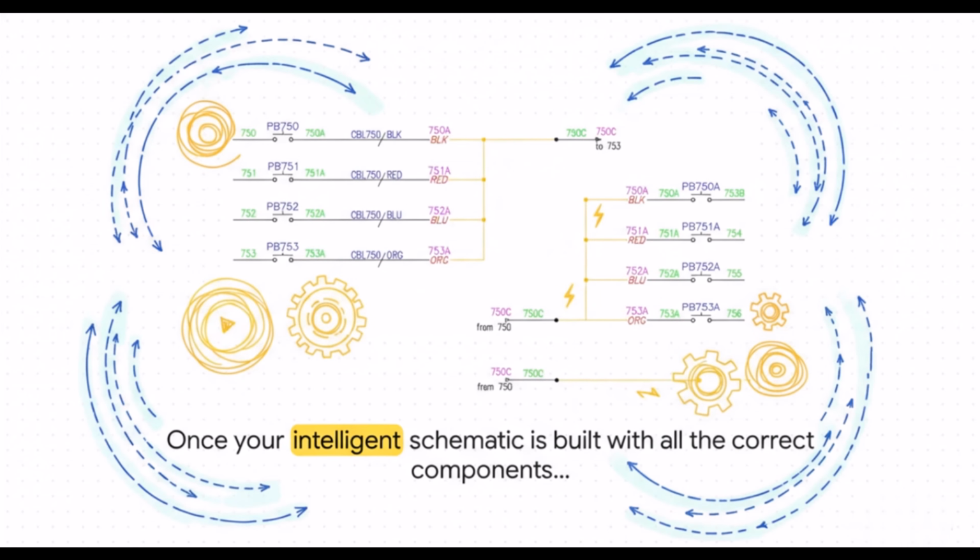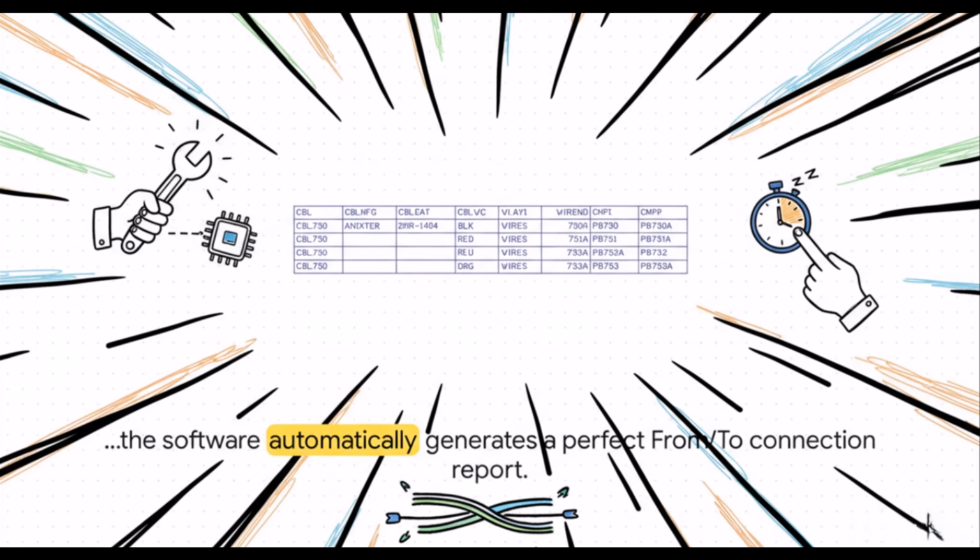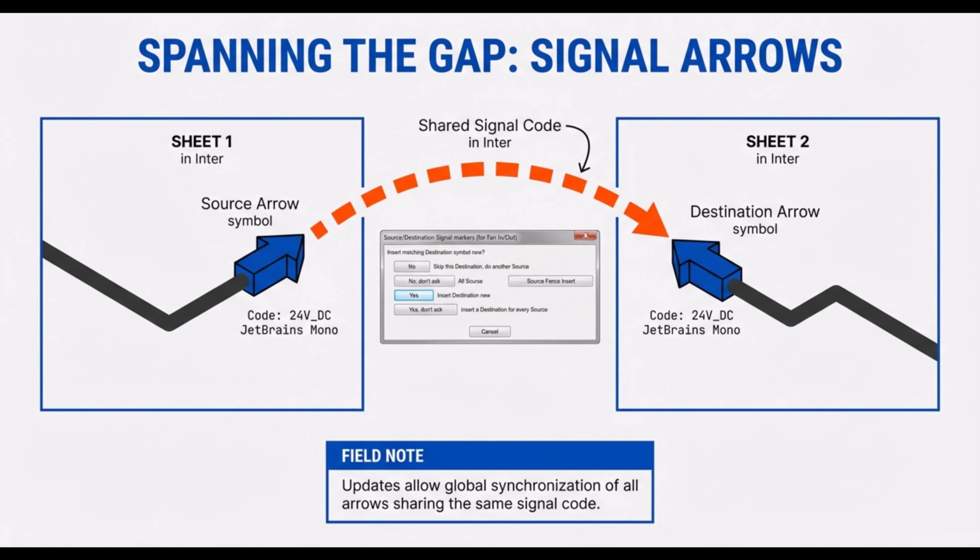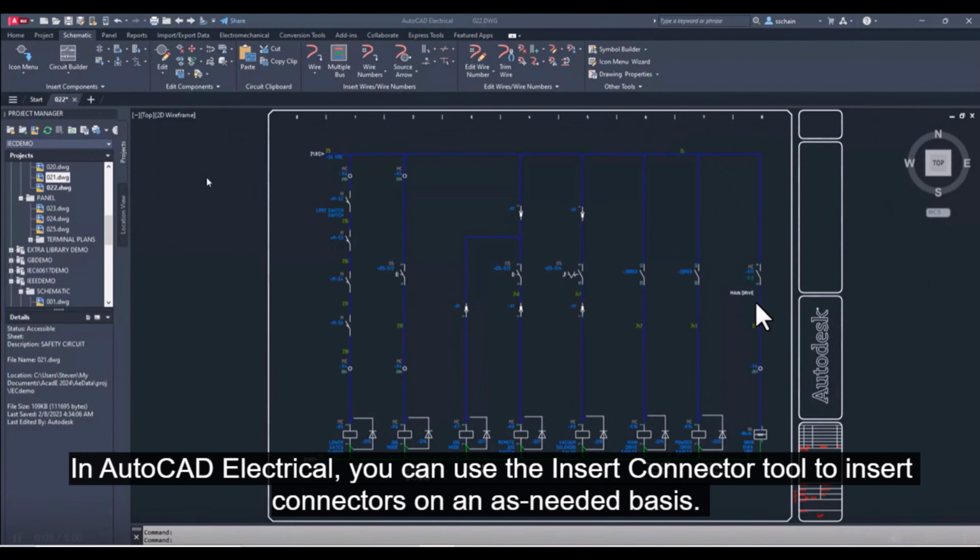We mentioned at the start that the drawing is just an interface. The real brain is that MDB file or .xls file running in the background. That's right. Usually Microsoft Access or SQL. Every single time you click, you are writing a record to that database. And standard AutoCAD users never worry about this, but AutoCAD Electrical users have this maintenance task called rebuilding the database. It's like defragmenting your hard drive back in the 90s. Sometimes the drawing file and the database files just get out of sync. Maybe the software crashed, or maybe you used a standard UNDO command one too many times.